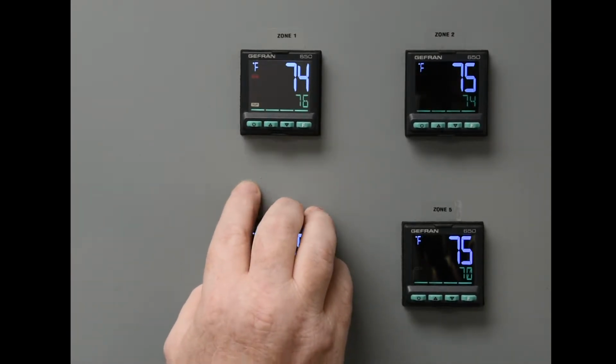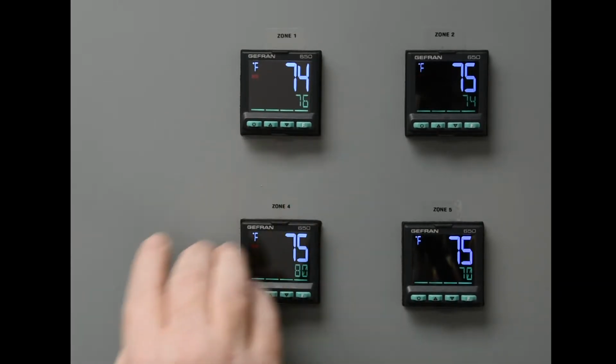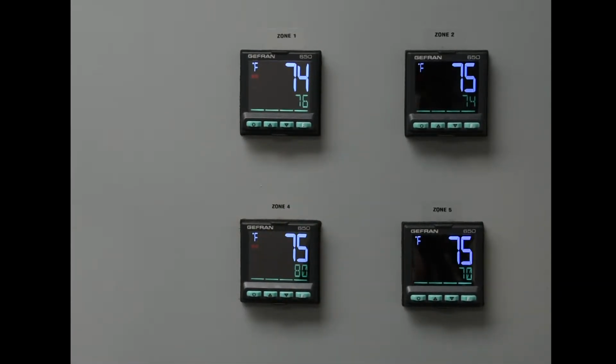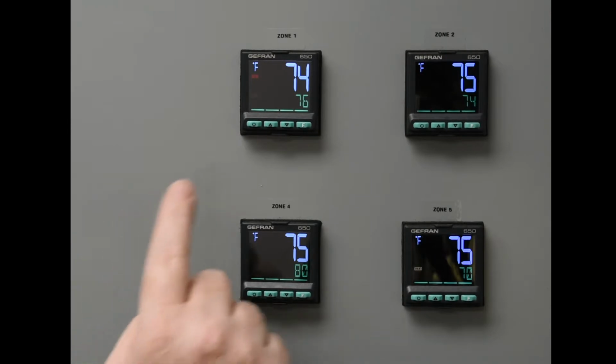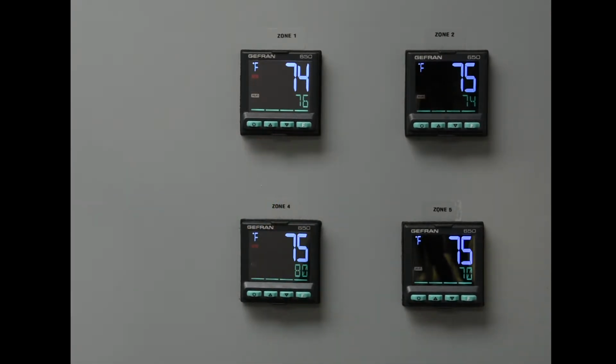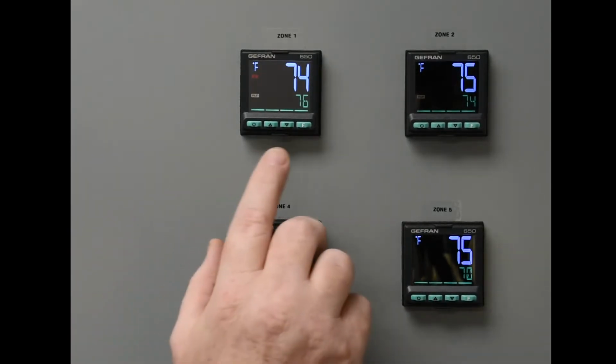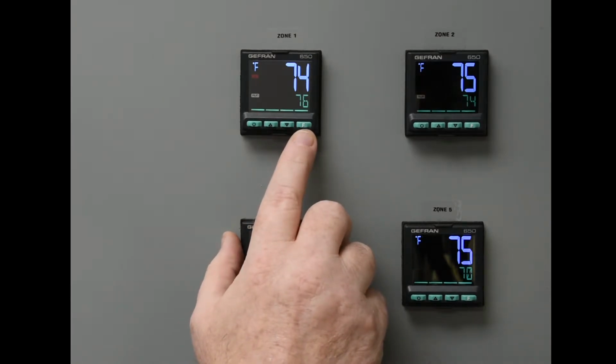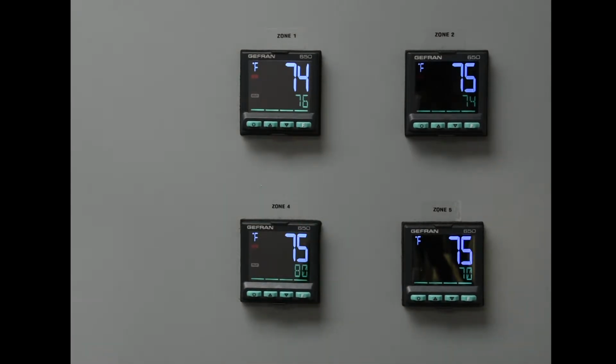To the right are the up and down arrow keys. This will allow you to change the parameter on display or the set value or process value. On the bottom right is the F key. The F key allows you to navigate among the controller menus and parameters. The F key will also need to be pushed to confirm the parameter value and select the next parameter.